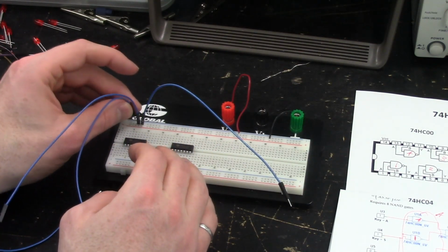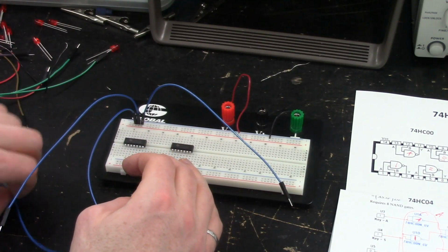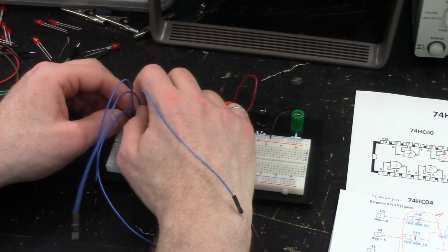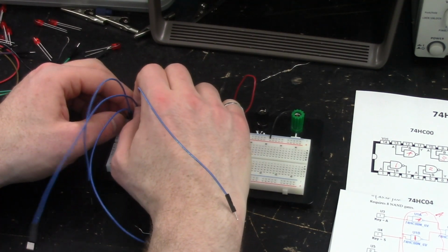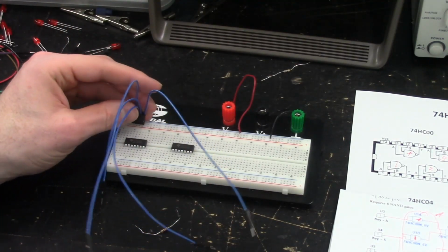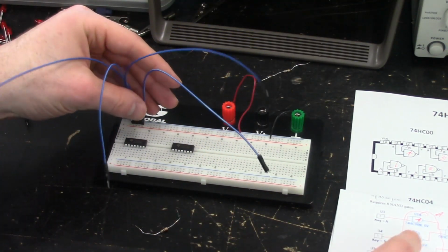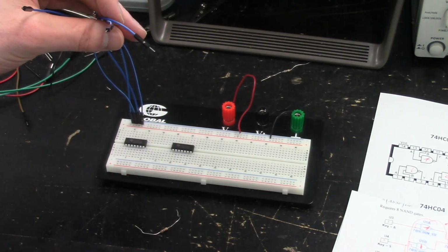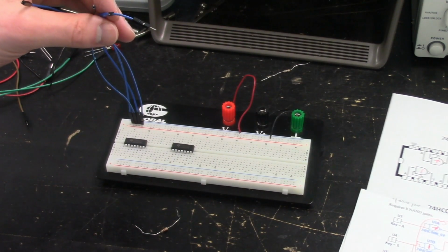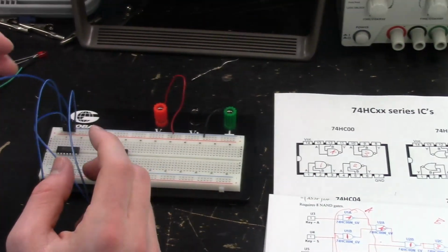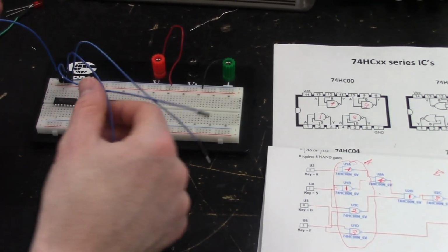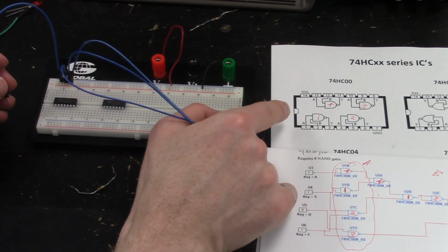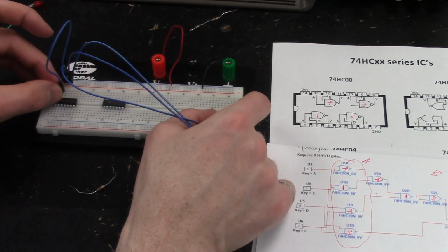And we'll just imagine that left to right, these are A, B, C, D. It's possible to move them like that even when they're all together. So that's alright. That's going to be our A, B, C, D up there, or I guess as we've called them, ASDF. Now we can check which of the gates these connect to. So A needs to connect to the input of gate number 4. There's our A there. And that's going to go to the input of gate 4, which is number 13 there.